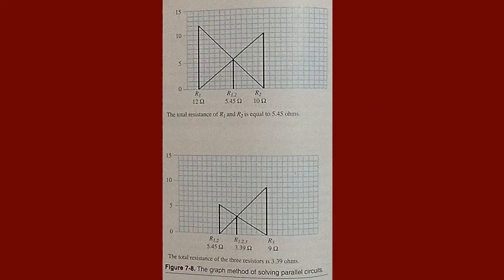The graph method is an interesting method of estimating the value of total resistance. The values of two resistances are expressed on a bar graph, like the one shown in figure 7-8. A line is then drawn from the base of the first resistance to the top of the second resistance. A second line is then drawn from the base of the second resistance to the top of the first resistance, making a crisscross. The total resistance value of these resistances may be read where the two lines intersect. A third resistance may be added, and the process repeated. This method is not considered to be very accurate, but it is a quick and easy method to check your work.